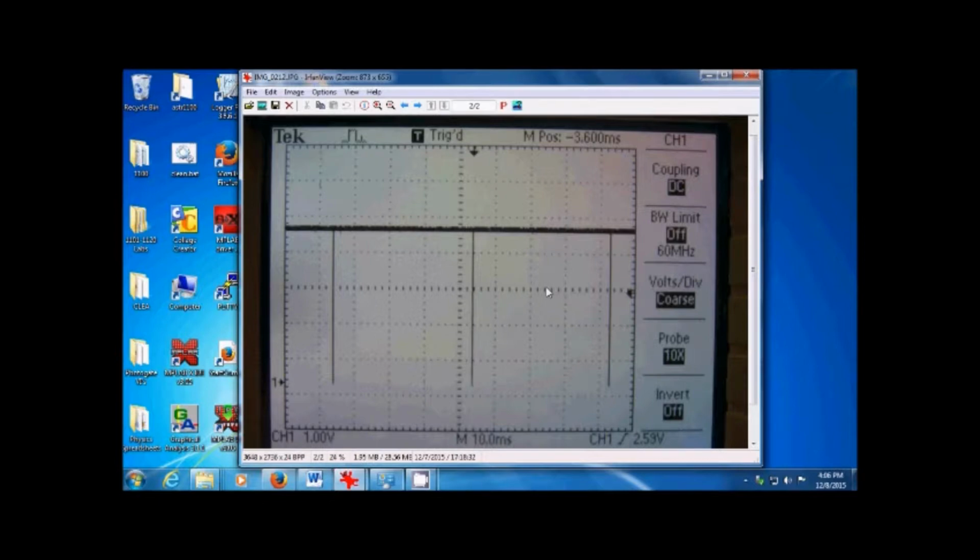So if you see something like this on the slow or the moderate blink rate, then what you should do is set up a stopwatch in MPLAB and time how long it takes to execute certain statements in your code. Figure out what's screwing up your timing and then fix it.